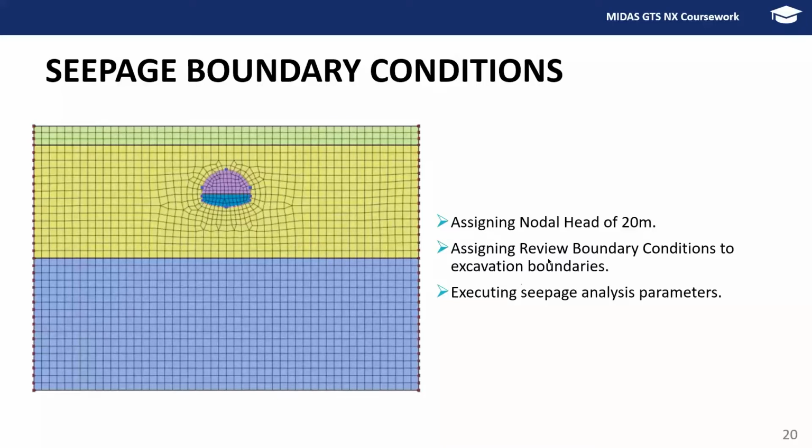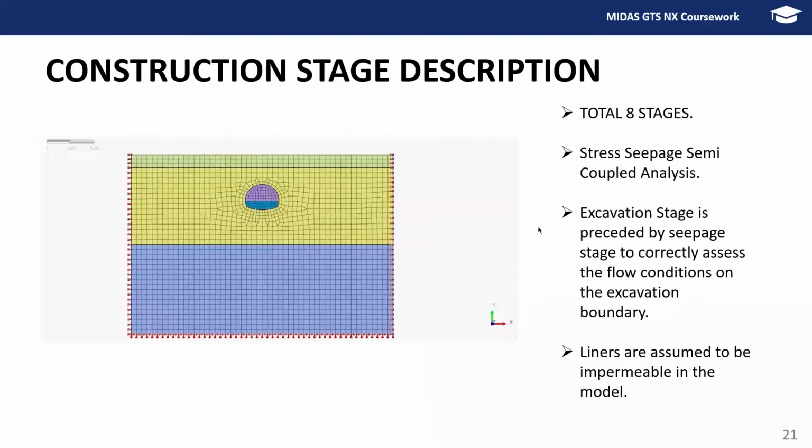And then we'll assign a review boundary. Review boundary is nothing but the potential seepage phase from where the water will seep into the excavation. And then we will execute the seepage analysis and then the stress analysis.